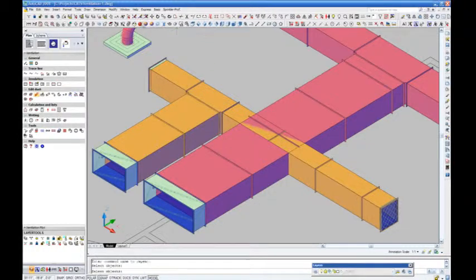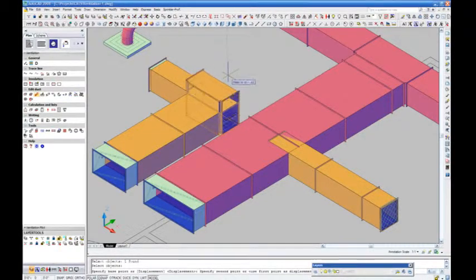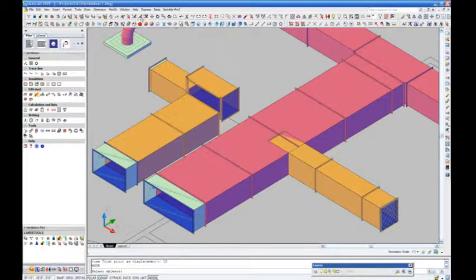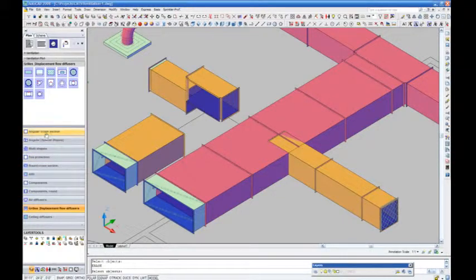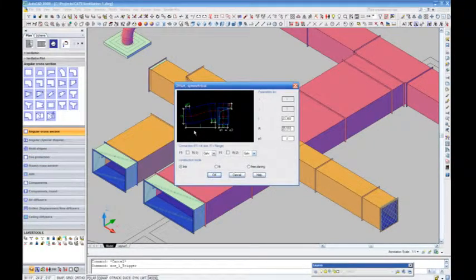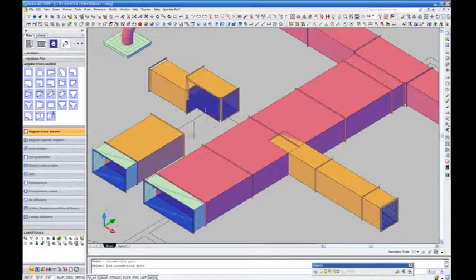We will now redesign our return duct at the collision point. We will eliminate the duct section to the right and raise our T 12 inches in the Z direction. We will eliminate the duct toward the fire damper. In the CATS Commander, we will select Angular Cross Sections and choose Offset. The Offset window appears and we select Fit. Select OK. By selecting the flange connections where you want to place the offset, the connection is made.